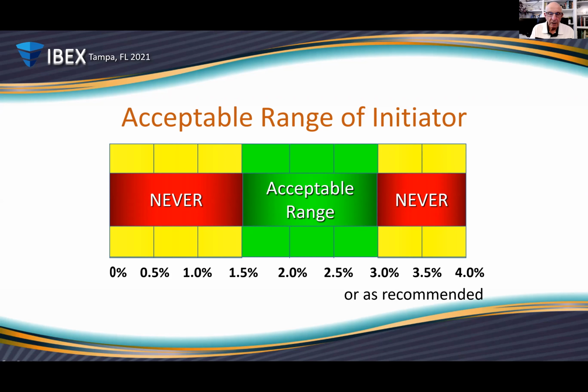So if you are spraying at 1.5% normal 9% AO MEKP, and then you switch to the summer blend at 5% active oxygen at 1.5%, you have a little bit more than half. So you're down at now 0.8% active oxygen in the system. Your gel coat's not going to properly cure.